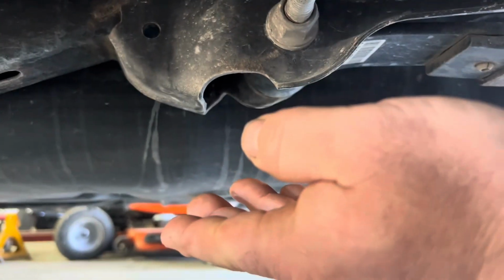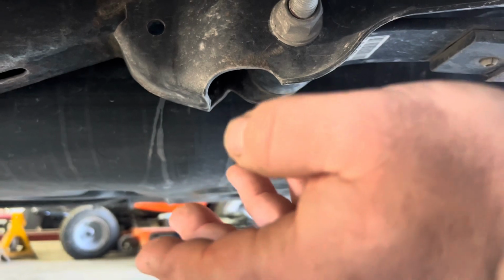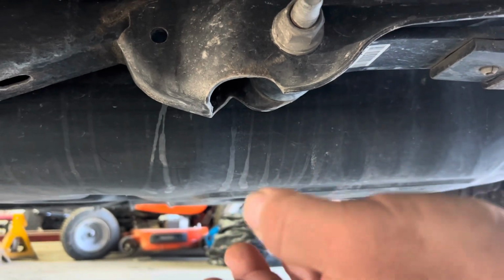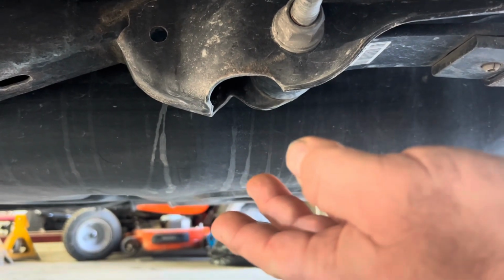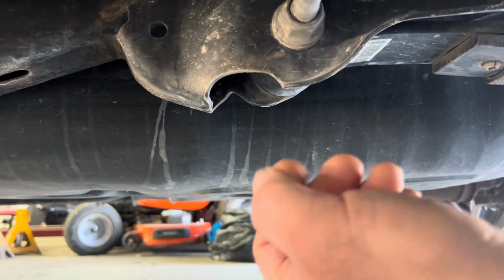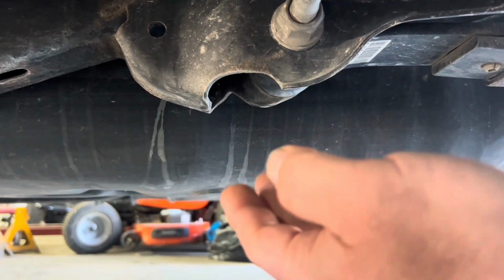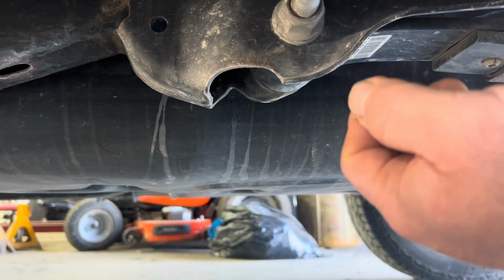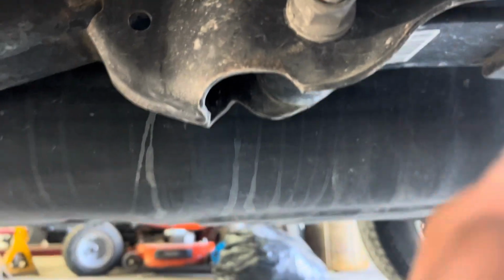We got it in last night. We got it all checked out. And I figured I'd film this and take you through what we did and let you know how to test on these things and hopefully get you to your diagnosis a little bit quicker. Now the first thing I noticed was that the fuel pump did not run on this thing. So I banged on the tank a little bit to see if we had a bad fuel pump. Maybe the brushes were bad. Maybe it'll take off and run. It didn't. So beyond that, we decided we'd just go ahead and throw the machine on it, check the codes.